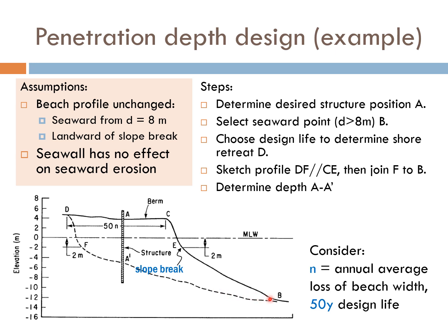So what it means right now is that we expect in 50-year time, this beach profile will be eroded to form this beach profile. And so if we desire to place our seawall over here, then we must make sure that our seawall should penetrate below this line. And how deep it is, it will further depend on the foundation design of this particular structure.